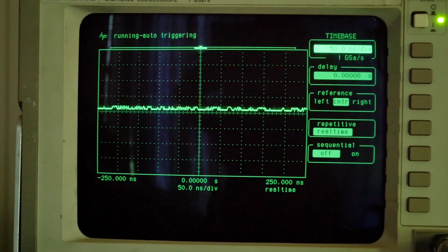My thoughts as to the origin of this is that we have an op amp with a gain bandwidth of about 50 odd megahertz running with a closed loop gain of about 10 to 1, so we would expect the unity gain bandwidth to be about 5 megahertz. And I suspect that what we're seeing in the error amplifier here is more output as the gain of the main amplifier is starting to trail away. I'm a bit concerned stability wise. I don't like to see this kind of high frequency content. Now this is barely going to appear at the actual output. It's pretty tiny even at the error amplifier stage. So maybe not a huge cause for concern, but definitely a little bit of a worry.